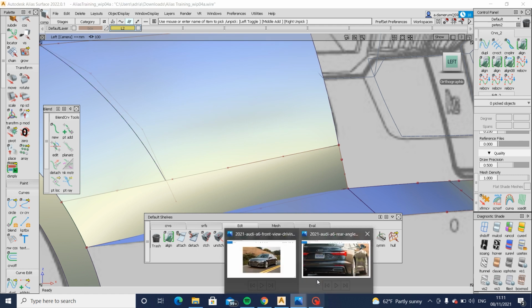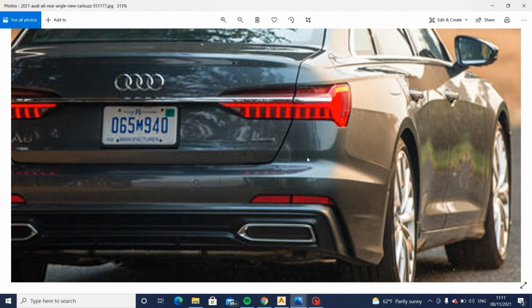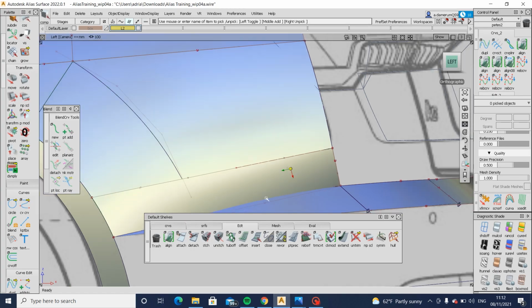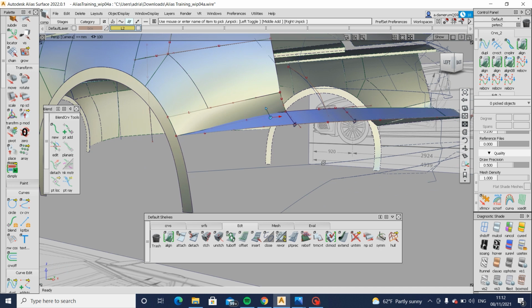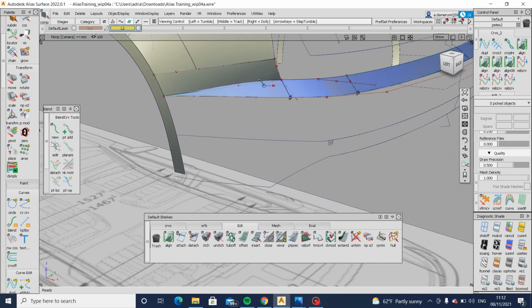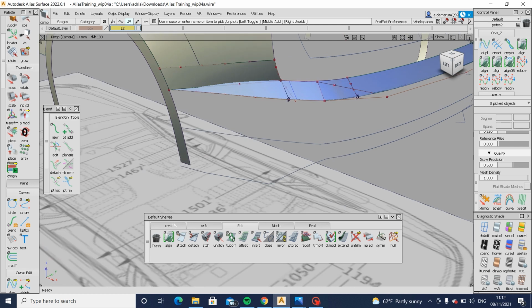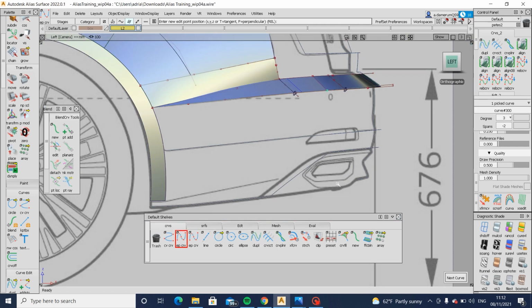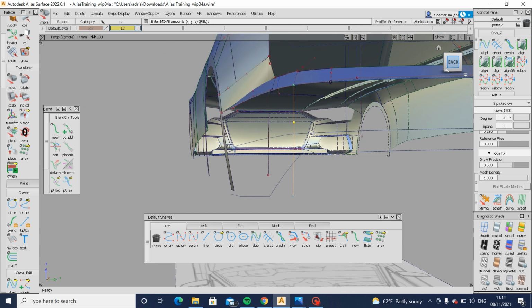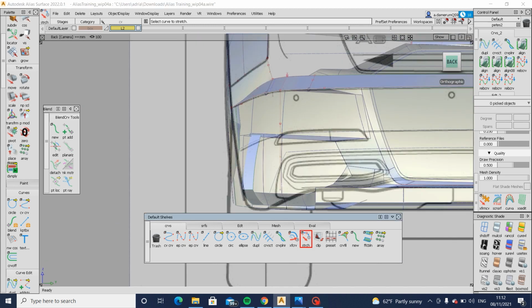Yeah, this is a tricky area. It's going to be quite difficult, but what we'll have to do is build a blend around here and a surface there, and then build another radius around. But let's concentrate on the lower bumper first. Okay, so let's untrim this actually. Delete the history there so it doesn't go crazy, and then we'll build a core for this, which should follow the center line. It'll be similar to the center line angle, and in rear view it will probably dive in a bit, so let's do that.